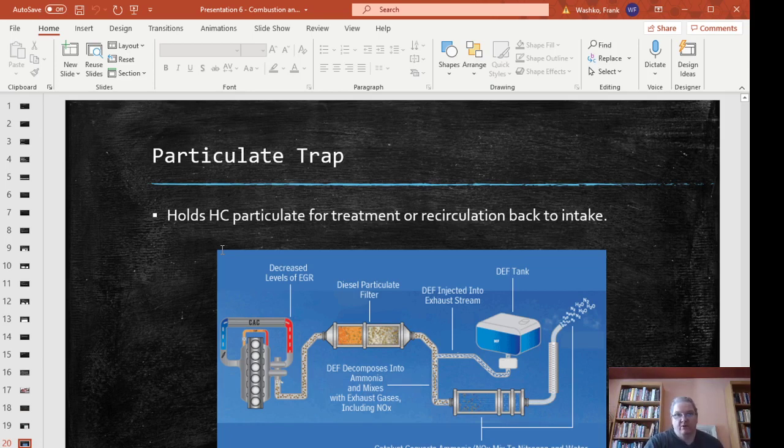And then whatever's left over, you can put through a catalytic converter, or, as you see in this one here, this also has a NOx trap at the end. So you could stack these different technologies up to get rid of as much emissions as possible, and the emissions regulations set what you have to meet in order to sell your product. I'm not that familiar with the diesel truck kind of emissions or off-road equipment.